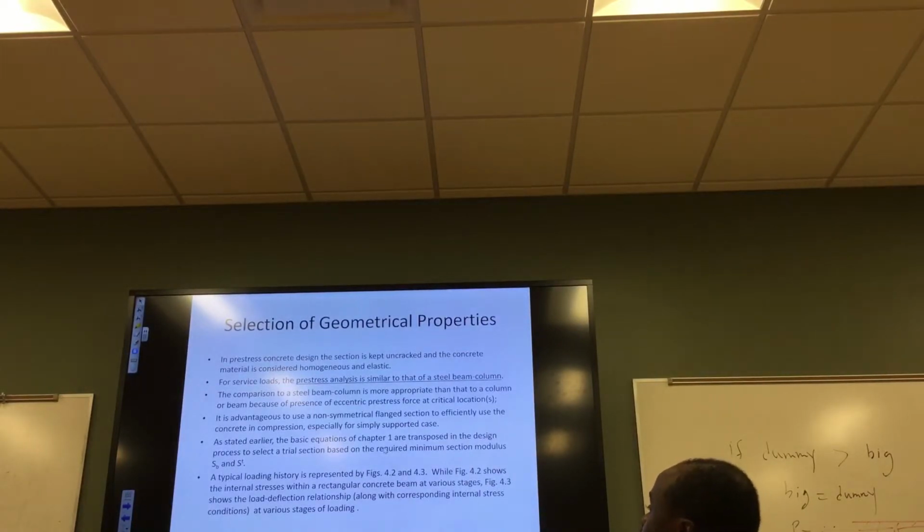Beyond service load, if you keep applying an overloading situation where you didn't anticipate, you put more load than you were calculating, then of course it will be cracked. But till that point, it is uncracked. And we assume this to be homogeneous, which is more or less true, and elastic. Now, the elastic part is kind of an assumption really, because we know creep is not elastic. So for service loads, the pre-stress analysis is similar to that of a steel beam column. I had told you this before in class once or twice, that our member, we call it a beam, but really it is a beam column.